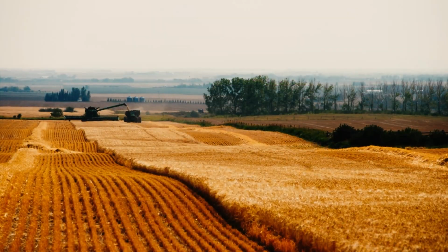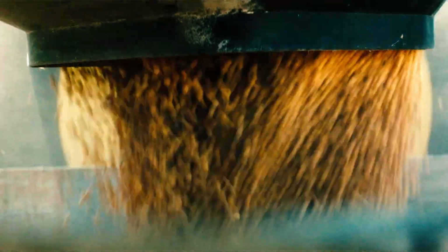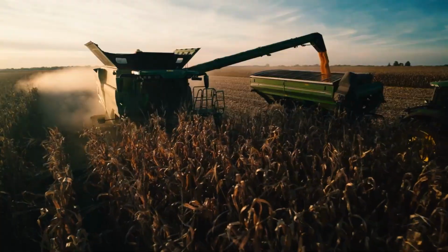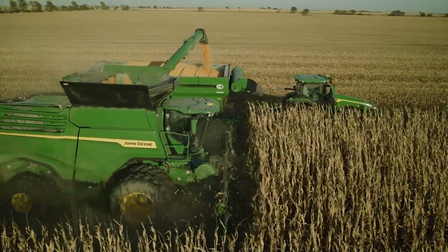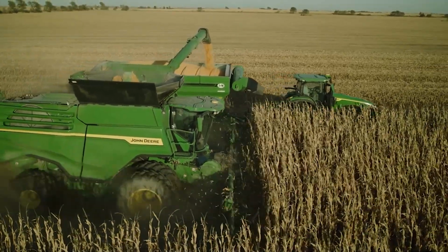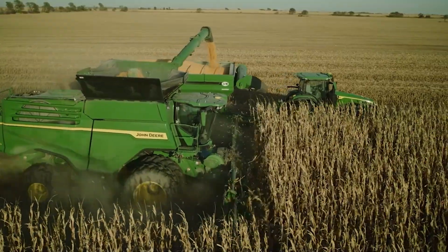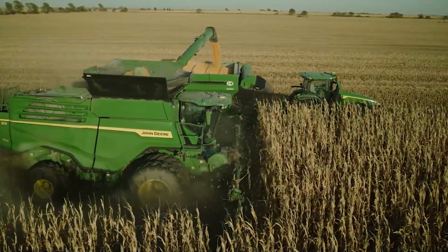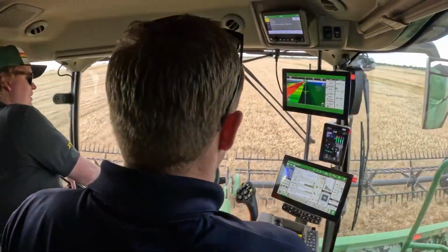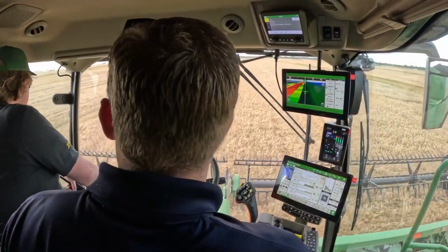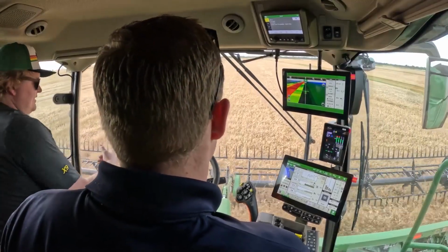There may be certain rare harvest scenarios in which a certain setting may be desired to be locked out from being changed. The good news is with Harvest Settings Automation, it can still be utilized, as there is a way to limit automation adjustments from a particular setting versus an all-or-none logic behavior. The system will then continue to monitor and adjust the other settings while allowing you as the operator to control the one locked out for manual intervention only.